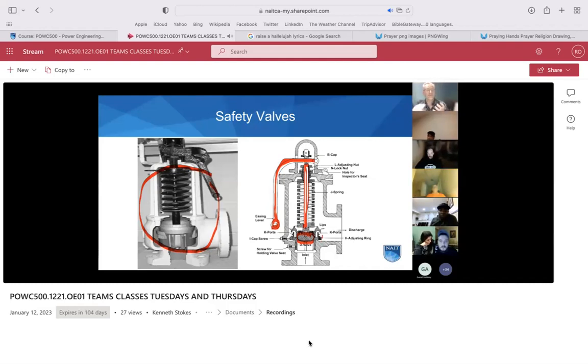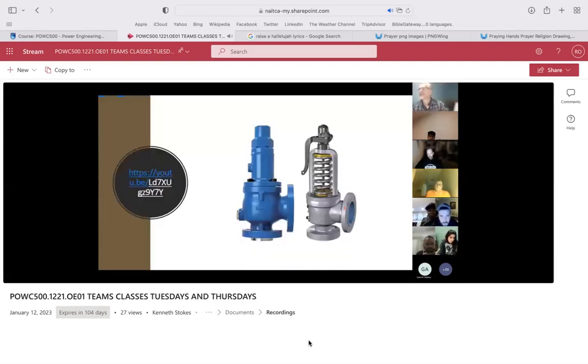This is why we call it a valve. A valve has a disc and a seat. The disc sits in the seat and closes off an opening. So the bottom of this is the inlet. This is where it would sit on top of the boiler. Pressure is going to be pushing on this disc where it says D valve. Pressure is going to be pushing on that, and the pressure created by the spring is going to push the disc down into the seat. And under normal conditions, pressure is lower than the specified opening pressure. This thing would be closed tight.